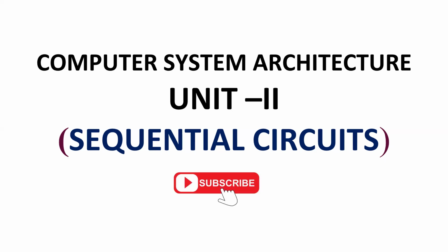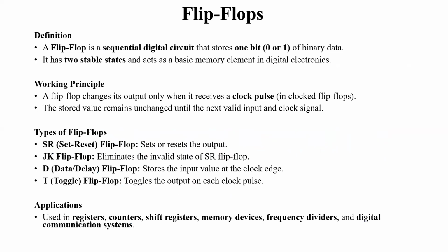Okay, now we can move on to the flip-flop concept. A flip-flop is a sequential digital circuit that stores one bit of binary data, whether 0 or 1. It has two stable states and acts as a basic memory element in digital electronics. A flip-flop changes its output only when it receives a clock pulse. The stored value remains unchanged until the next valid input or clock signal. We use the flip-flop for storing one bit of binary data.